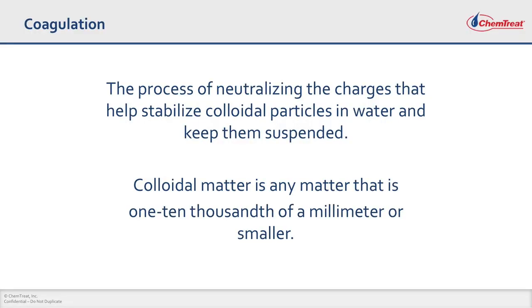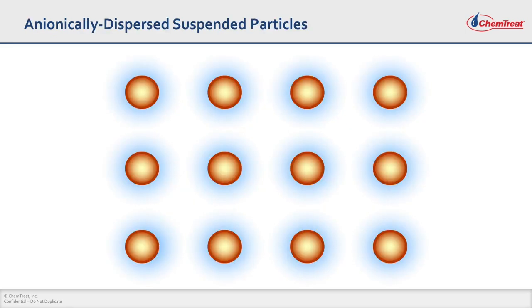So first, coagulation. What is coagulation? Well, it's a process of neutralizing the charges that help stabilize the colloidal particles in water and keep them suspended. Particles, when they come in contact with water, have this surface charge around them that keeps them suspended and keeps them from settling. And the whole goal of coagulation is to bring particles together and then help them separate from water.